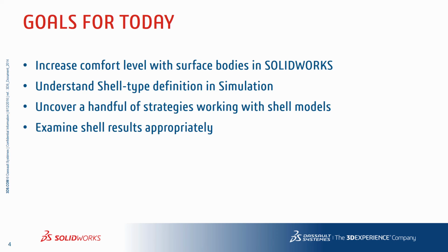And along the way in that, I'm going to uncover my best strategies for working with shells, especially as you evolve to having hundreds of shell bodies. And then finally, I'll spend a few minutes talking about the different results you get when you have shell elements, as well as a few pointers if you're looking for including fastener results or weld analysis.